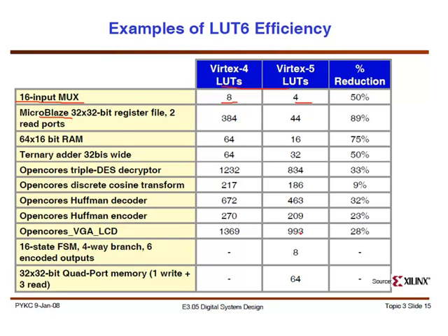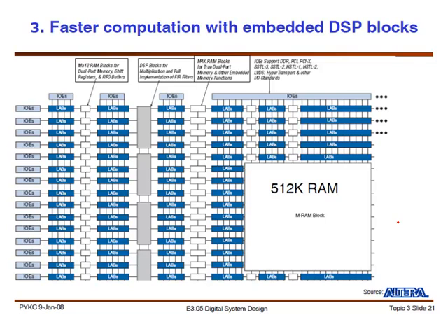So basically when they looked at these different benchmarks, they saw that yes, I'm going to be able to do more reduction in terms of the LUTs used. So that again determines that you want to use a 6 LUT or 7 LUT or 8 LUT, and this study is going to be repeated every couple of generations, because things that might have made sense with the previous technology might no longer make sense with the new technology.